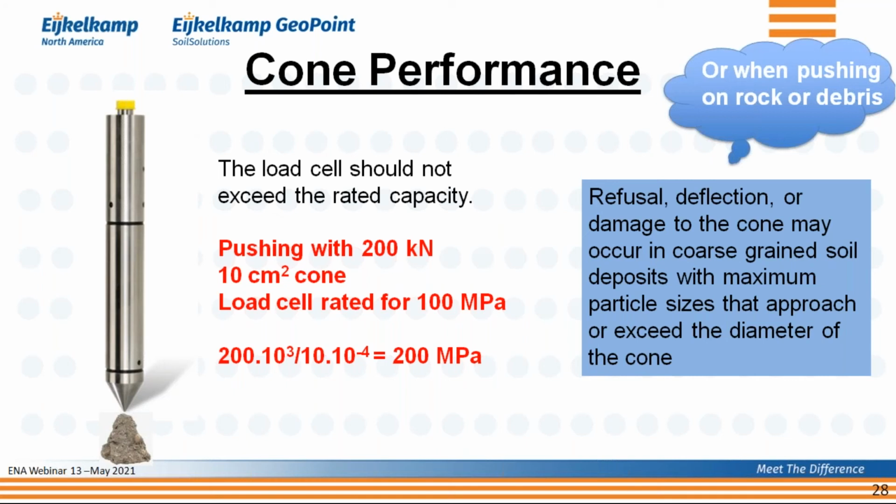People try to keep pushing through rock or through construction debris, pieces of concrete. It will not work. You will very easily overextend your load cell. And when you do that, your cone is going to be broken or no longer functional, and you have a problem. So that's something that you need to be aware of and avoid. That's one part of the cone.